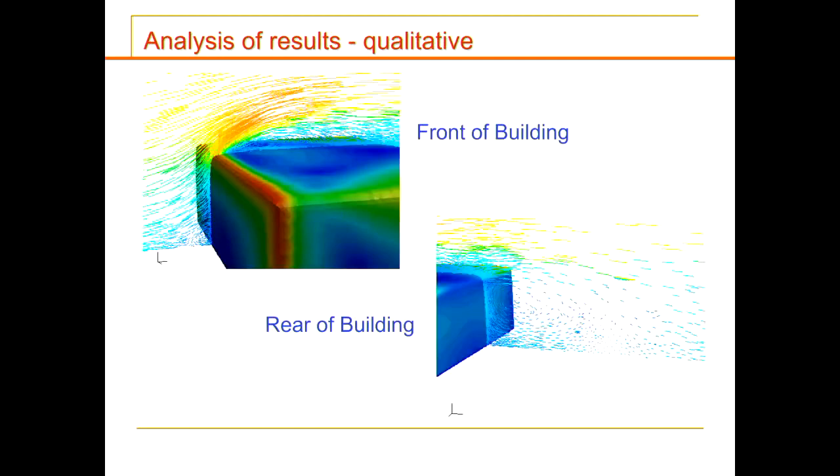So this is looking at flow over an obstacle. You have the front of the building, let's say, and the rear of the building. This picture shows the flow impacting the front of the building, and then you have a flow separation as it climbs up the wall and flows over it. Depending on how fast the flow hits the building and then deflects, the recirculation region would increase. This was generated using a streamline approach. The colors indicate the pressure impact by the wind, or the velocity.